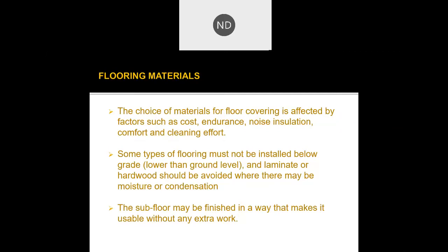Flooring materials. The choice of materials for floor covering is affected by factors such as cost, endurance, noise insulation, comfort, and cleaning effort. Some types of flooring must not be installed below grade, lower than ground level, and laminate or hardwood should be avoided where there may be moisture or condensation. The soft floor may be finished in a way that makes it unusable without any extra work.